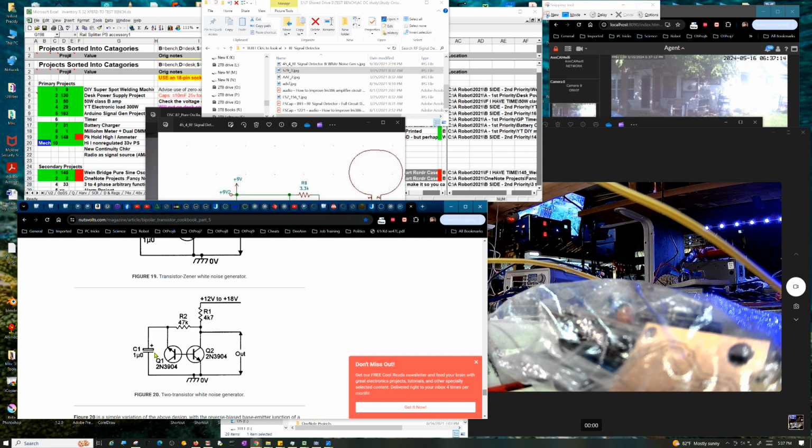Like I said, that does make a high pass filter. Maybe he's just trying to eat out the flicker noise or something, the low end stuff, because it'll probably form an RC filter here somehow. So it might be a good idea if you wanted to limit it. The one I built had a noise curve like this, a definitely sharp curve, with the noise drastically increasing as you approach DC. This would probably eliminate some of that.